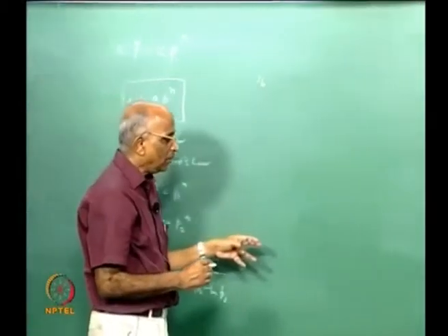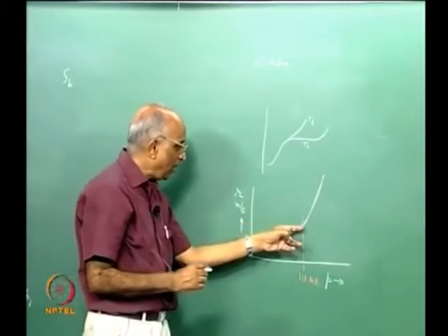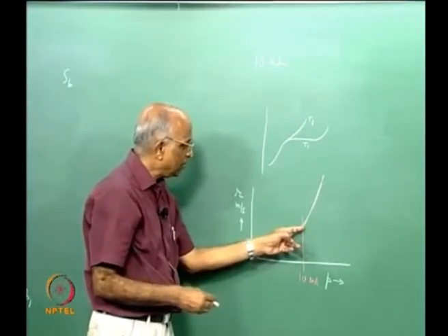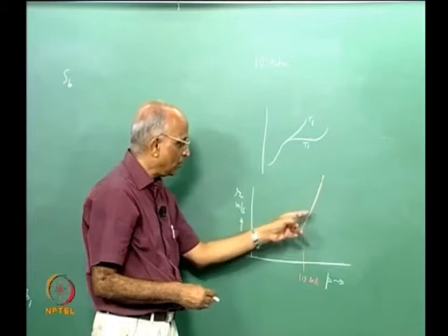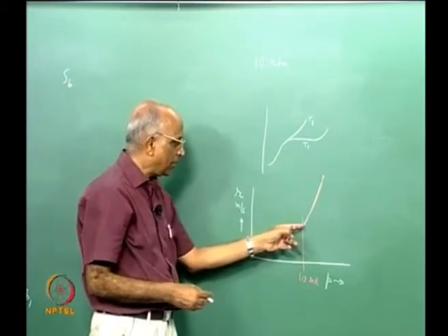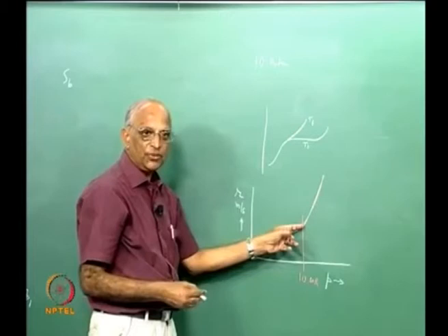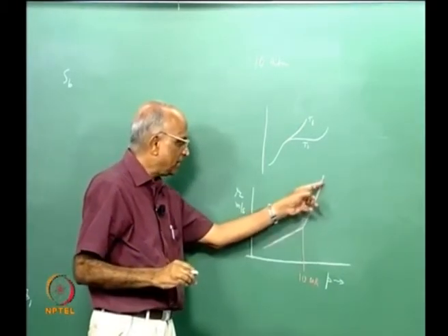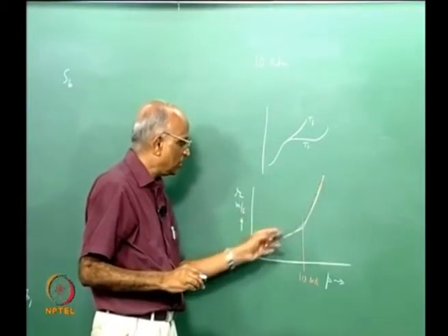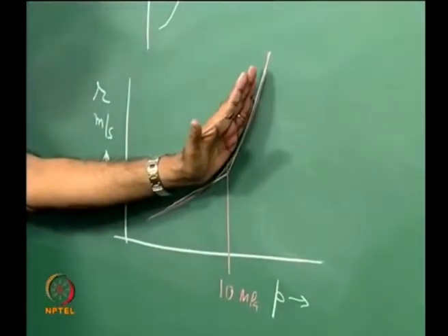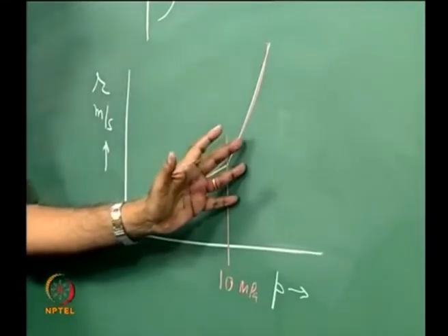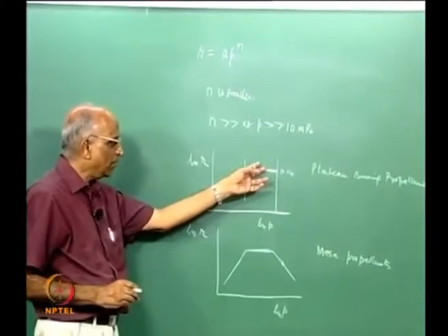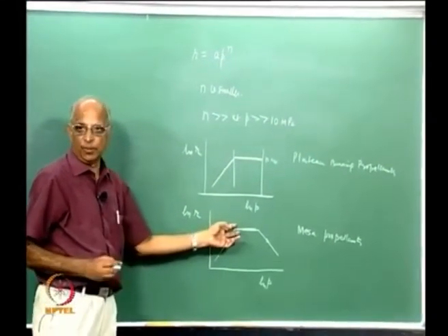Thereafter we said that at high pressures the reactions happen directly, that means instead of having a dark zone you do not have that. That means at high pressure temperature increases from surface temperature directly to the flame temperature, more heat gets conducted, therefore n is higher, therefore you have this procedure like a small n followed by a large n for the double base propellants. Then we said, well, if I add some salts I could have something like a plateau burning propellant or a mesa burning propellant.